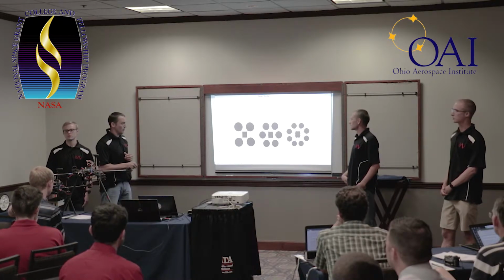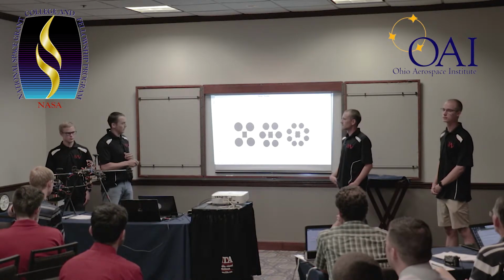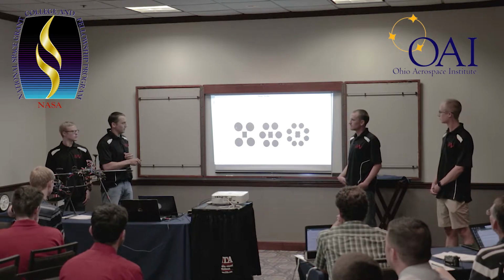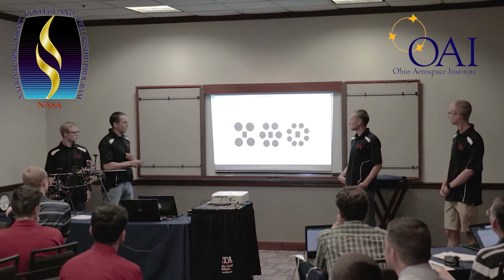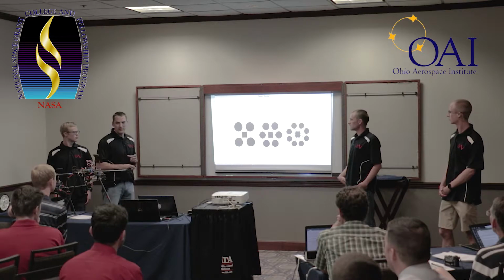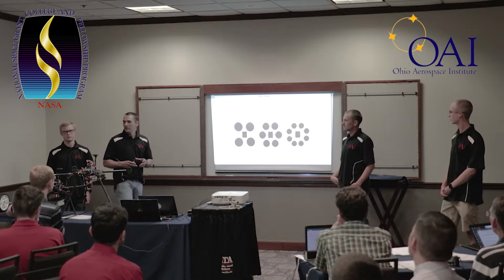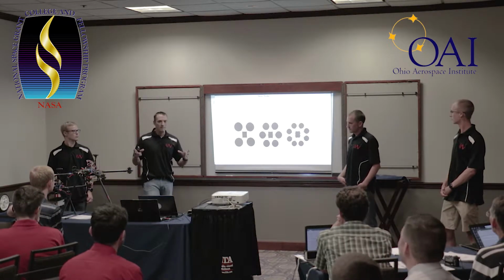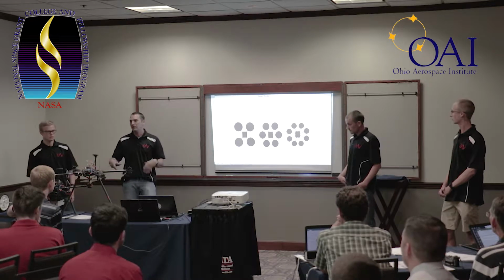However, if you look at the aerodynamics and the efficiencies involved in such systems, what happens is when you increase the number of disks, this one bit of disk area, if you call this disk area, the disk area individually gets smaller, right? So there's a maximum disk area that you can actually have and still be efficient.